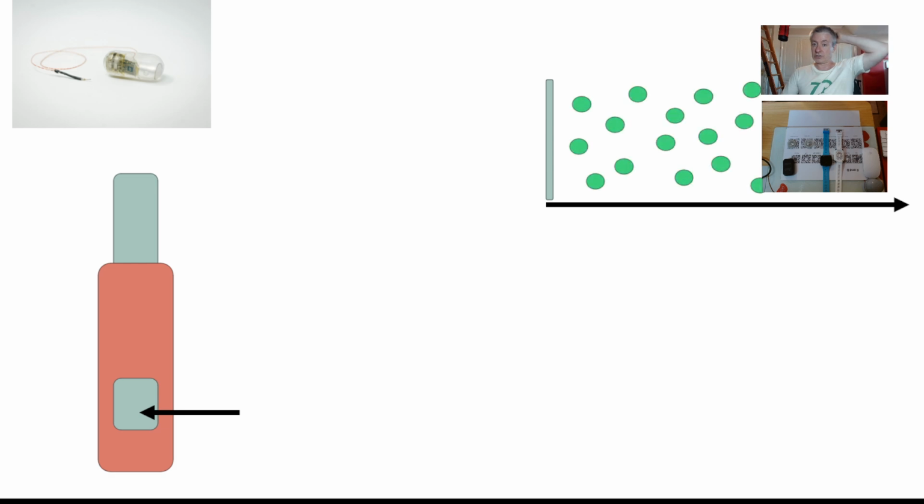So I want you to imagine that we're looking onto this electrode now, and this electrode is sitting in a solution, and in this solution there is an electrochemically active molecule. The black arrow indicates distance from electrode. Before we turn the electrode on, and in glucose sensing, when I say turn on, it generally means you apply a voltage and you measure the current, and that's called amperometry. So before we turn it on, we've got all these electrochemically active molecules, but nothing's happening because we haven't applied the potential. So at T0, everything is fine.